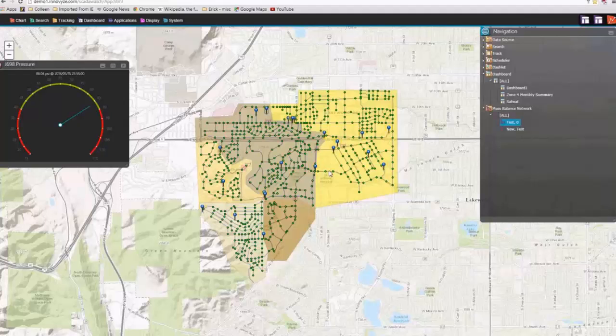We can take care of problems in SCADA data. If you've got zero values, negative values, null values, we allow you to say should the program just average the ones before and after to get a value? Should I just take the one before or after and use that value? Do you want me to flag somebody? There's a lot of internal metrics and internal flexibility and ways of getting around the data to make this a